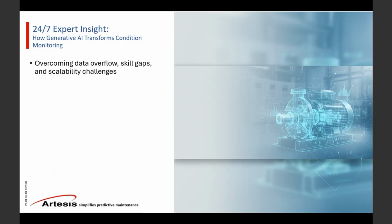But here's the catch: the information comes from different worlds, right? Because it covers multiple aspects of condition monitoring, you need to understand electrical behavior, and you need to be comfortable with spectrum analysis for mechanical faults, and you also need to process context data such as flow and pressure and operating conditions, and to understand what changed and why it changed.